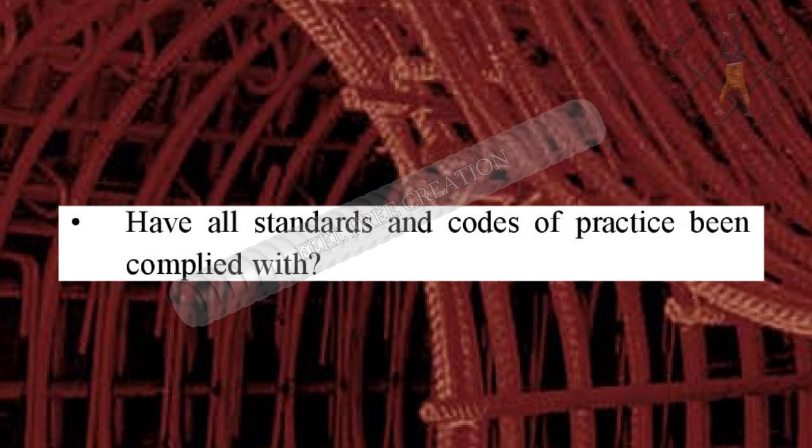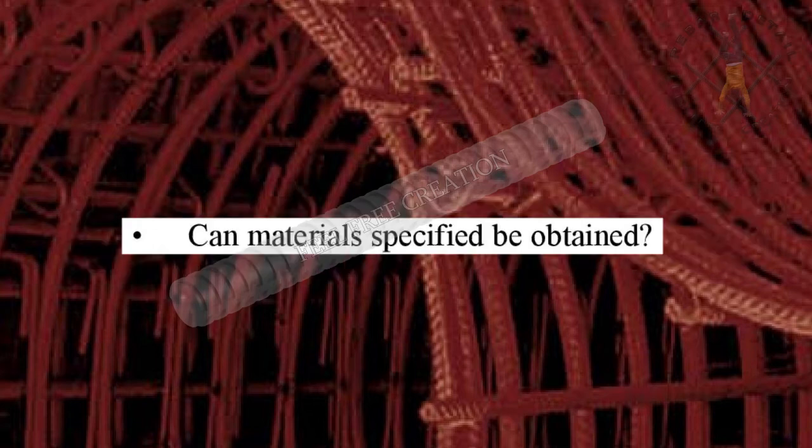Point 7, have all standards and codes of practice been complied with? Point 8, are setting out dimensions correct? Point 9, have checked dimensions been included? Point 10, do running dimensions agree with overall dimensions? Point 11, can materials specified be obtained?